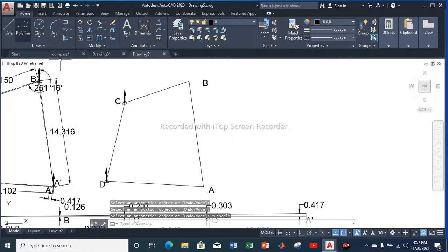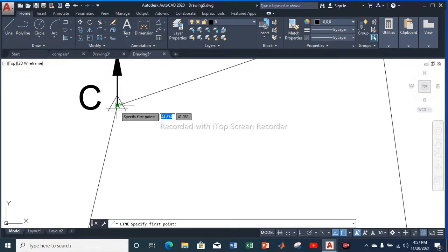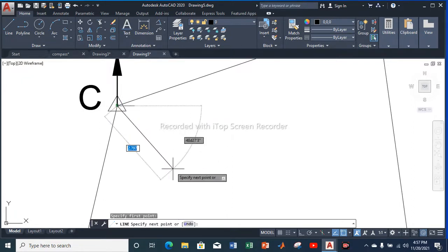So from my point C, I need to make a stone marking at a distance of 7.902 meters, at a clockwise angle of 155 degree 30 minutes. As I have already explained before, because of the same logic, I need to subtract 90 degrees in this case as well.